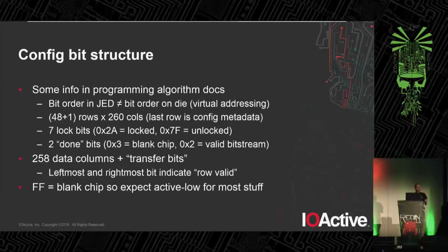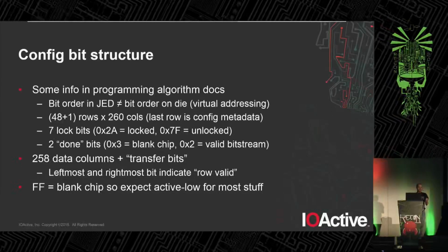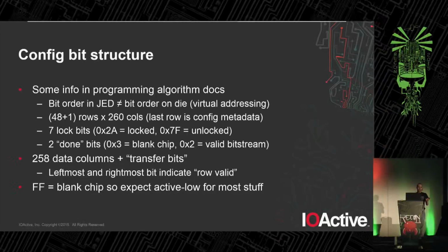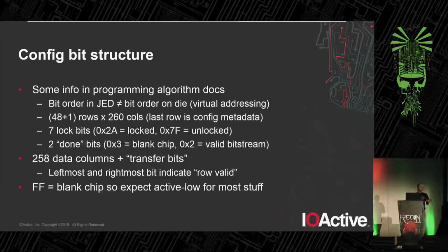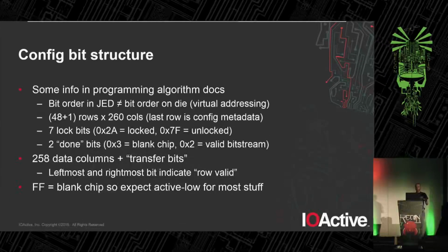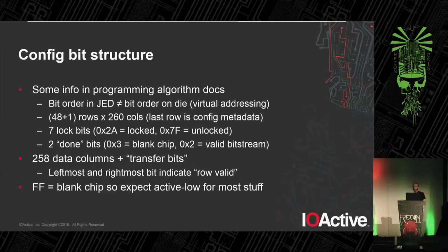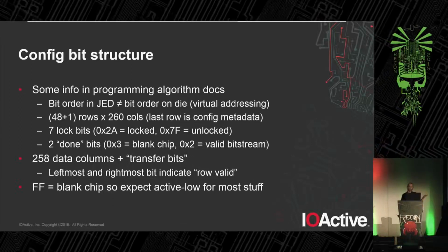And the other intuition we can get from this is that since it is EEPROM-based, then FF is going to be the state of the memory when the chip is blank. So therefore, we expect most of the memory on the device is going to be active low. So most things should be turned off when the bit is high and on when the bit is low. We just don't know exactly what that bit does yet.